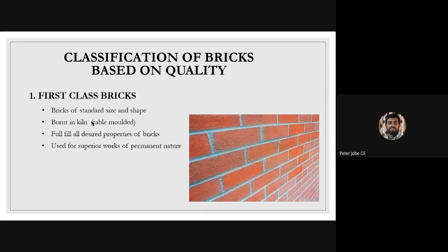So we'll just see again what is meant by first class bricks. They will have a standard shape and size. They will be burnt in a kiln properly, and they will fulfill all desired properties of bricks, and they are used for superior works of permanent nature.